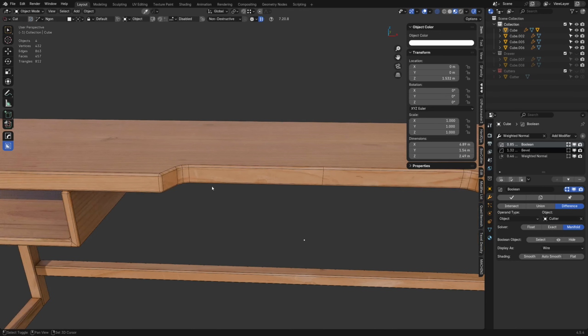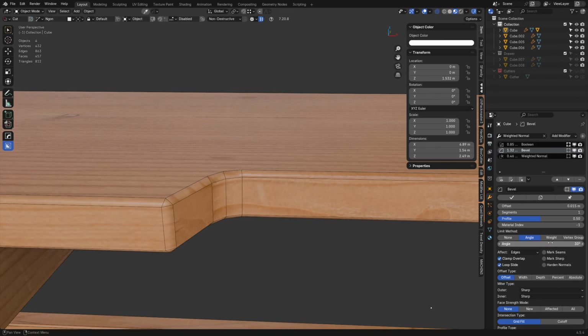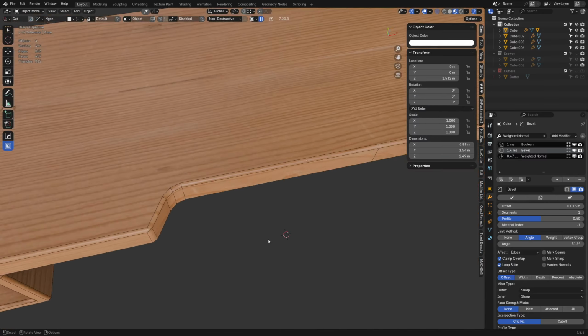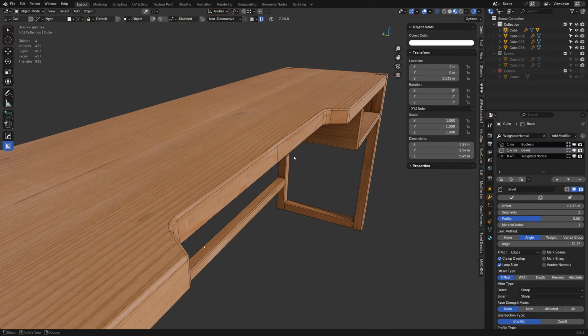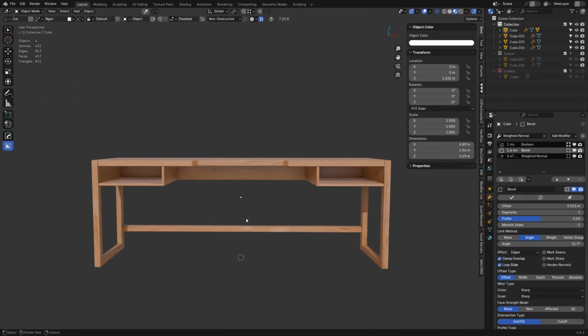You can see the bevel's not taking effect on it. Let's say the bevels were taking effect on it by accident. That would be because the angle amount's too low. It looks something like this. Just bump the angle amount up a little bit or add more bevel segments when you do a bevel like that, on the actual mesh, not the modifiers. So we end up in this situation. It's not too bad, right?